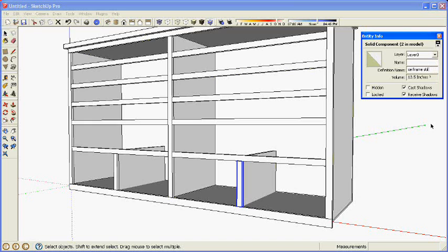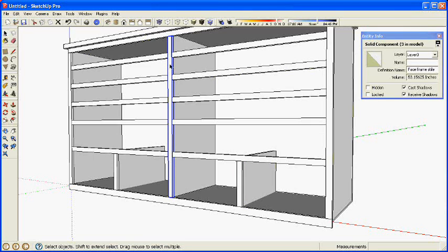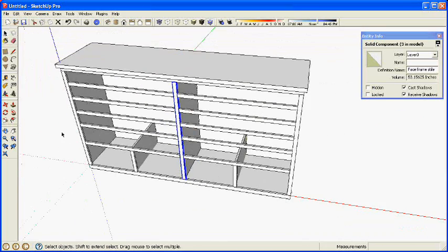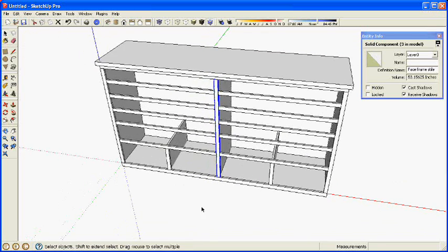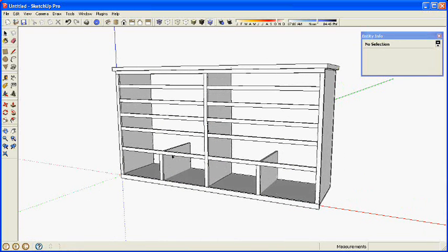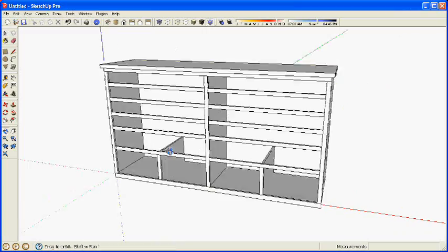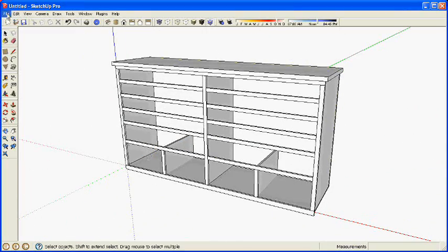This face frame style, sometimes it's difficult to decide what to call things, but we'll call this short style. And I'm going to go ahead and leave the center face frame style related to the outer ones. At the moment, that's okay. If we were to change the sizes of these outer ones and wanted to leave that one alone, we'd need to use make unique. Alright, so we're finished with that, and now we're back to where we were at the beginning of the video.